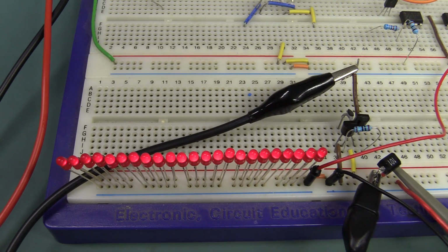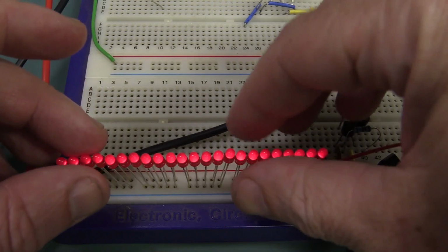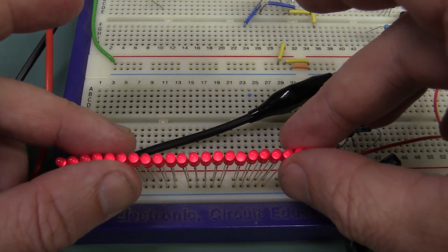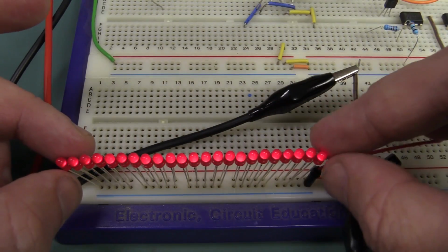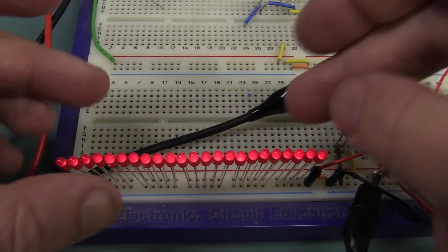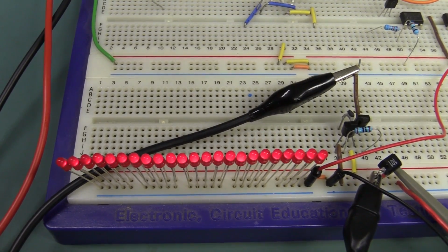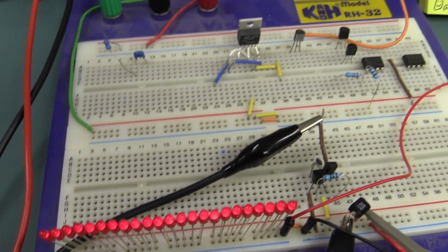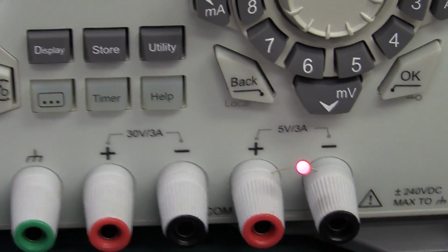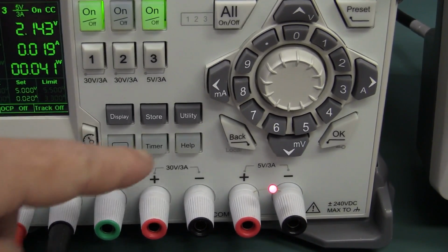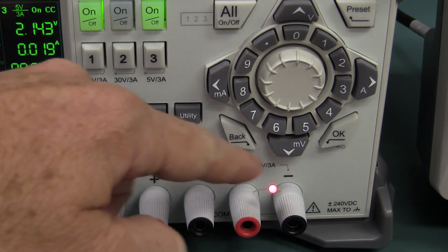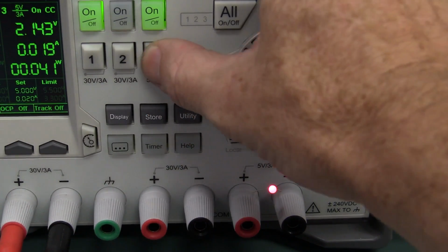Now, I've put fixed exposure on this camera, so we know that there's a total of 12 milliamps flowing through these LEDs on average. So that means the average current for each LED is only half a milliamp. Okay, half a milliamp, 500 microamps, and we're getting, you know, a reasonable brightness here. So I've got fixed exposure. I've got the same LED over here, and as you can see, that one, well, I'll show you that at the same time. That one is exactly the same LED, but I've got that at a fixed current of 20 milliamps. So that's basically the maximum current. And it's not a huge amount brighter.